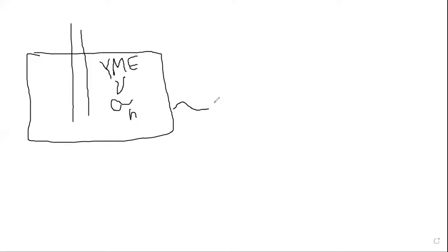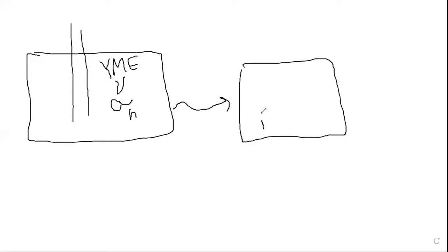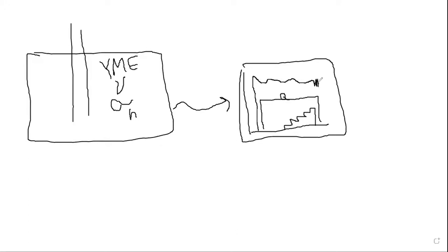So, several parameters define your reservoir. Then apply the pumping schedule, which is mainly the pumping rate and the fluid used, and with the pumping rate and your proppant schedule, get the pumping pressure that you need to design and estimate from the design.